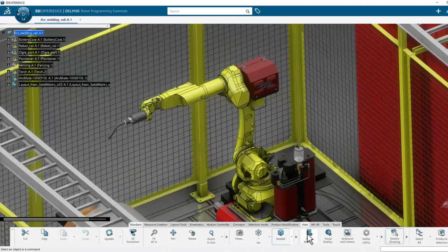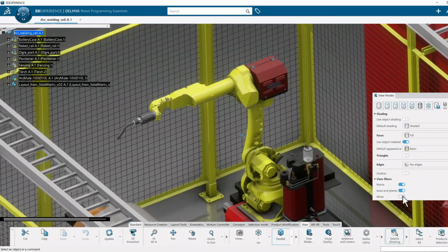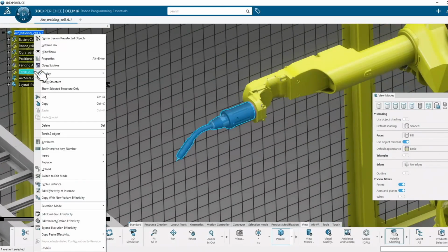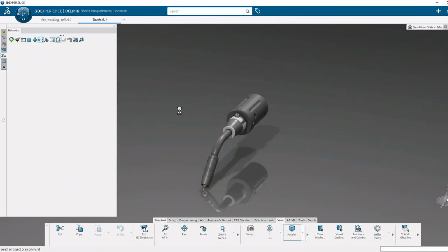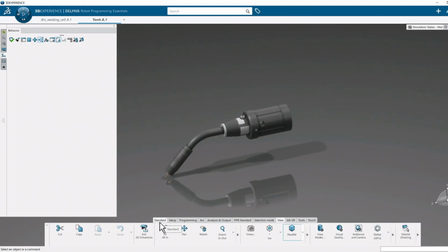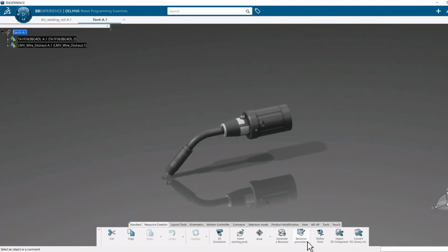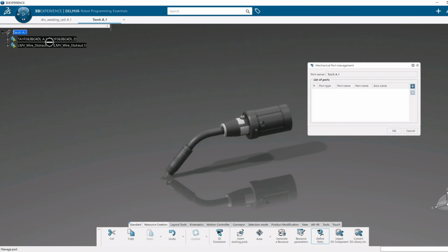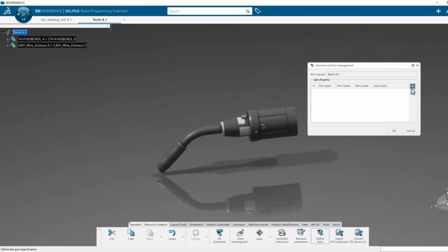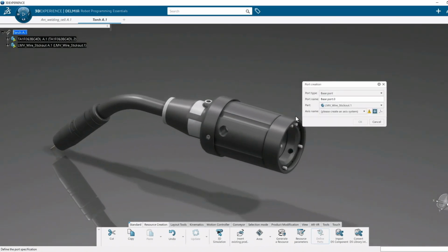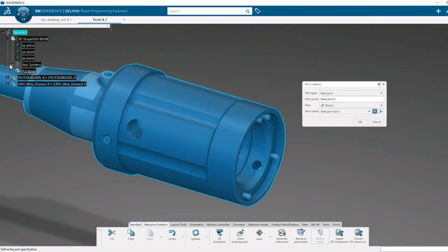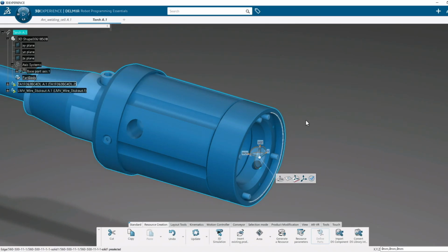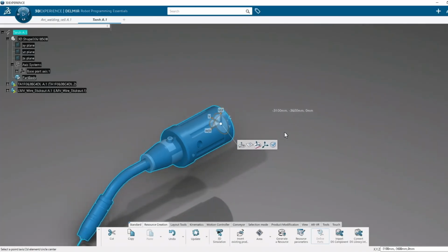Now, when it comes to things like the tool center points and such, regardless of the origin of your data, this happens to be a torch tip, but the same tool that I did with that unique grabber that I just brought in from SolidWorks, it's really just about, for realism's sake, defining how this part's going to attach to the robot itself, which also has a base port, and then defining exactly where this robot is going to touch on a part. Now, for this one here, defining a base port is, again, just grabbing on geometry here. We can use a simple edge of a circular face or a circular feature, and then that's going to enable us to go ahead and put the base port right in the center of that. So now drag and drop of our tooltip onto our robot.